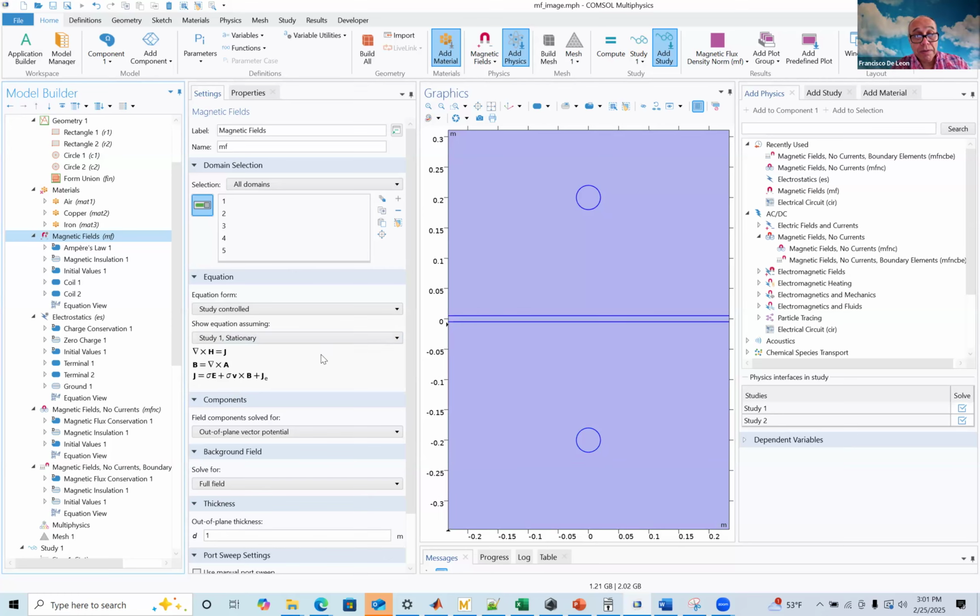The conductor is stationary and the magnetic field is moving. It's the same thing to have the magnetic field moving or the conductor moving in a magnetic field. The only thing that is important is that it changes with time. In that way, there is induced voltage, and if there is conductivity, there is induced current. Those are the eddy currents, if you wish.